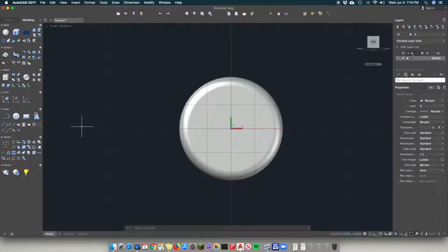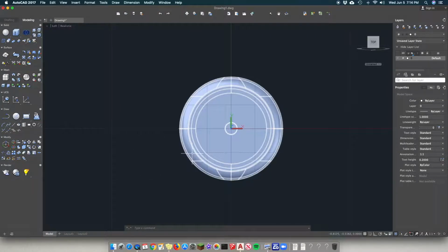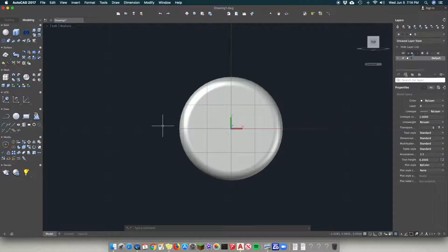Okay. All right, so now we're going to need some layers, because what we're about to do is, if you actually were to take apart a yo-yo, there are these cut pockets. There are 4 cut out spots called pockets on this face, so that it's not a solid piece of plastic. So what we're going to do is make some circles and some lines to make that shape. We're going to copy it around and then make those cuts. But it's going to get really messy unless we have some layers.